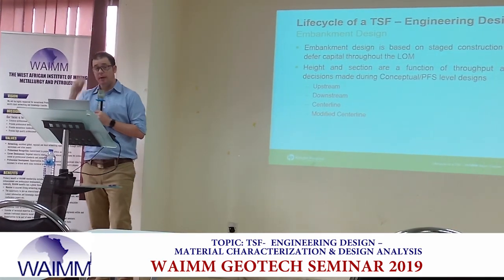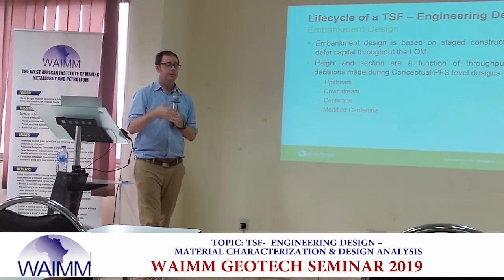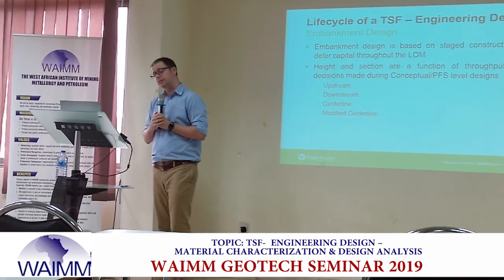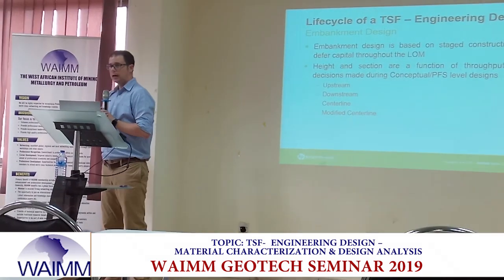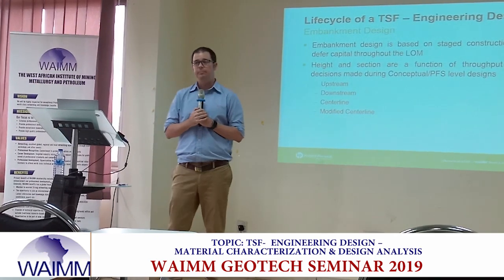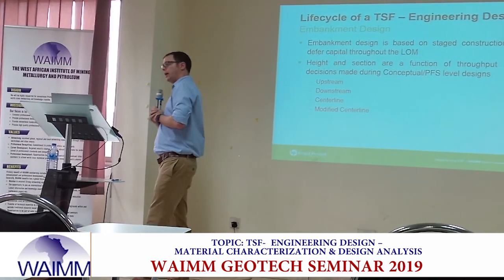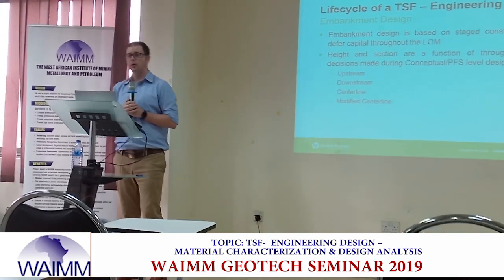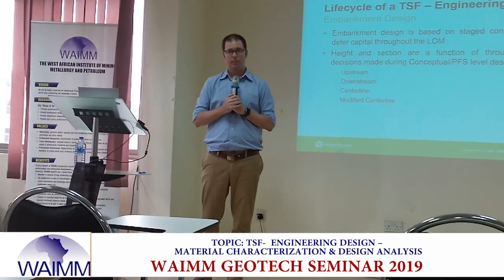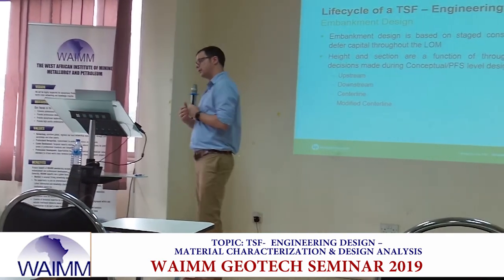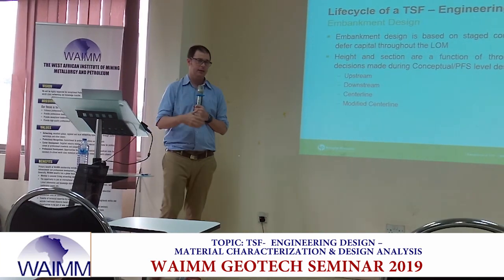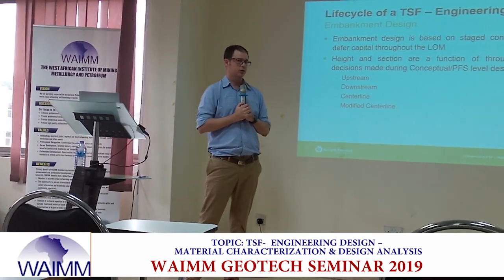Those decisions are going to be based on your material characteristics. They're going to be based on your climate. They're going to be based on your regulatory commitments. So for instance, here in Ghana, we classify our dams class A, B, or C. Class A and B must be raised using the downstream method, or otherwise agreed upon with the regulatory bodies. A Class C facility may look at centerline and may look at upstream raised dams, depending again on agreement from the regulatory agencies.